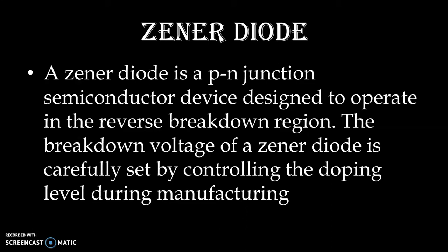In normal PN junction diode, we know that we always use PN junction diode in forward biased condition. When we apply forward voltage to the PN junction diode and when we increase the voltage beyond a knee level, then the diode starts its conduction. Voltage across the diode becomes constant and current increases. This characteristic of forward biasing is similar in case of Zener diode also.